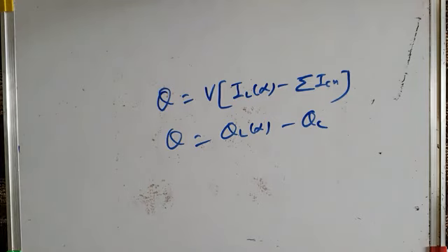First, you may have turned on all the TSC branches. Then reactive power control is done by alpha control of TCR, and then you may have to switch out some of the TSC branches, and then in different steps, by alpha control of the TCR branch, continuous reactive power control is done. That we have tried to understand with the help of the graph and characteristics. So more on it in the next lecture.